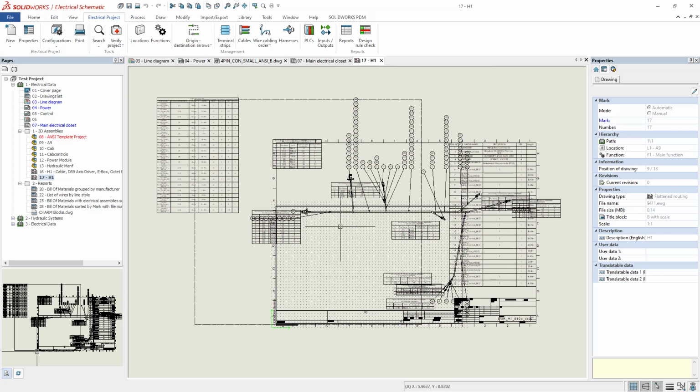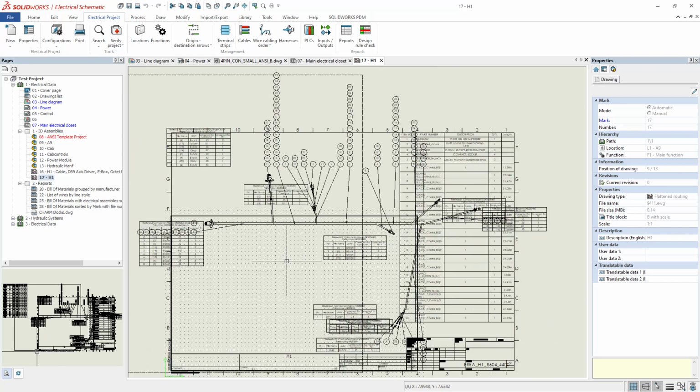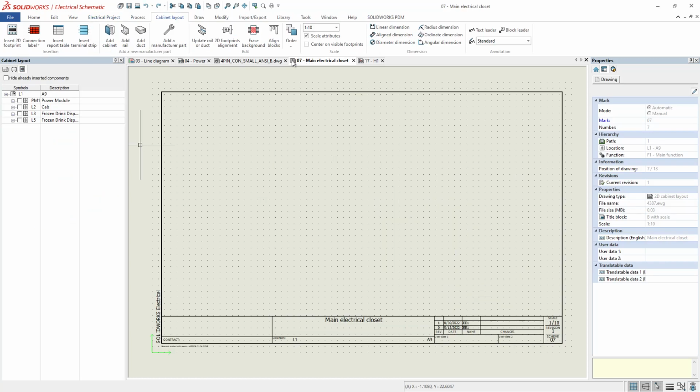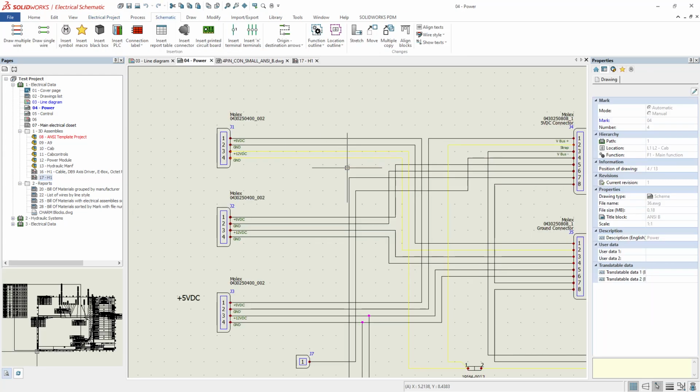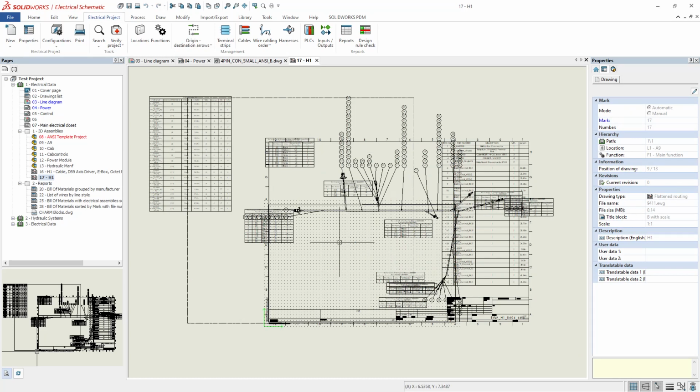There's a few different ways. Some folks like to populate the tables back over here on the electrical side rather than let the SOLIDWORKS mechanical side populate them. If you want to just pull the actual harness and leave the ballooning and the tables for the electrical side, I like that way because then the tables are all dynamic and linked back to the schematic, right? If I make a change to this or I change the pinout, the connection tables that are here are dynamically linked. Right now these are just static tables because you pulled it from the mechanical side.